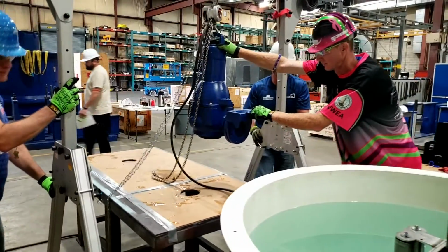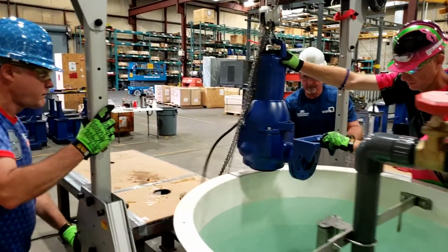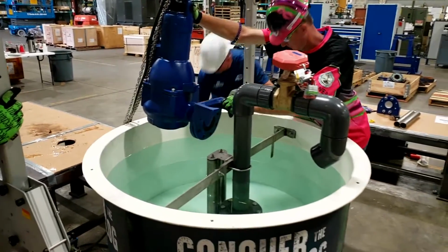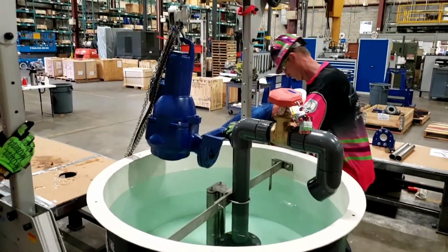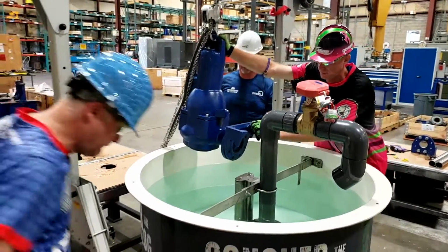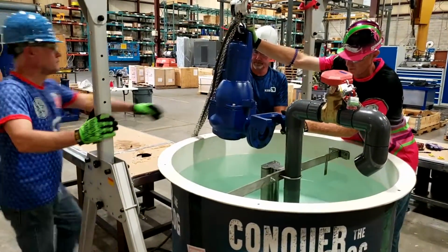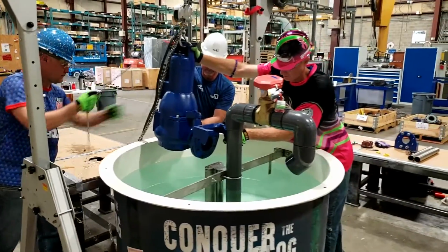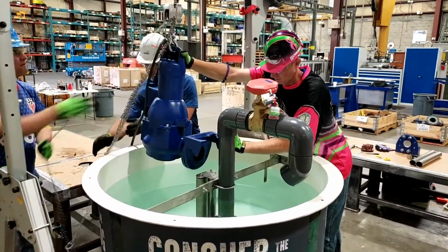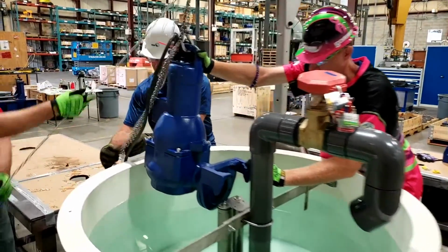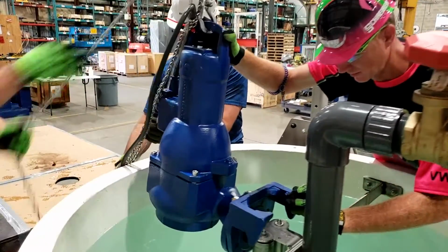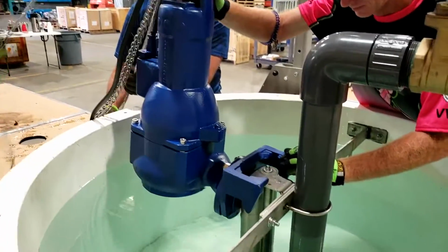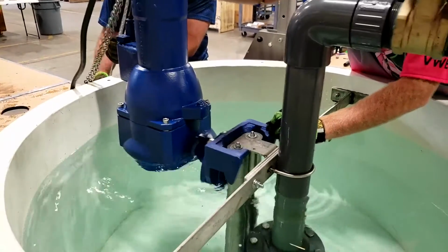You may now move the gantry with the pump attached to the wet well using a minimum of 3 people. 1 person must be in contact with each end of the gantry, and another person must be holding on to the pump to eliminate excessive swinging of the pump. Once in position over the wet well, lock the wheels and begin lowering the pump using the chain hoist.